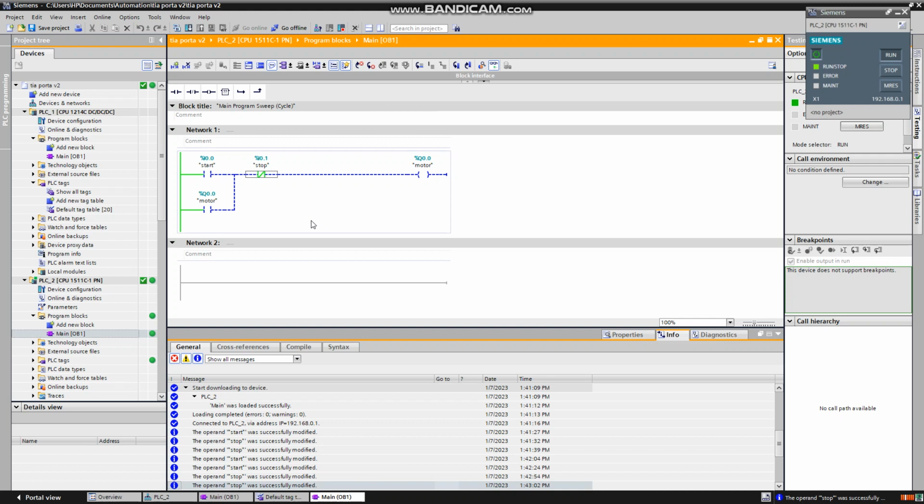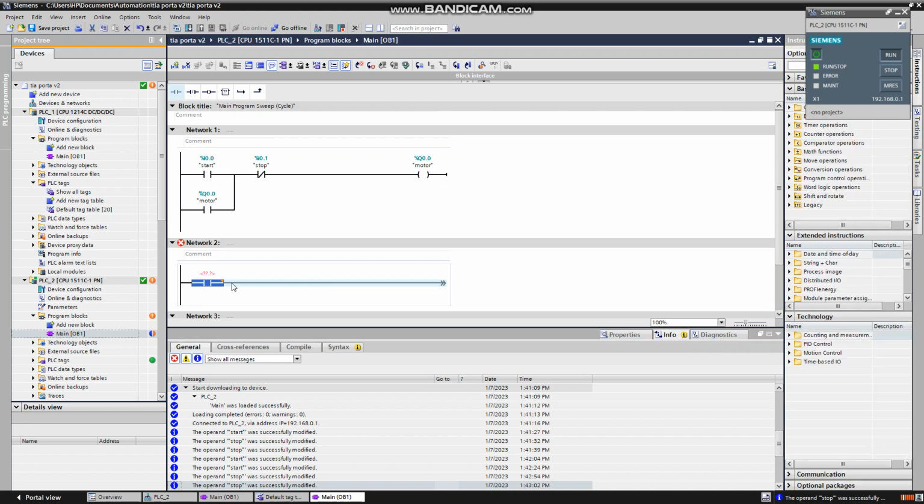Also we can make this with set or reset functions, and they are good and eligible functions in PLC in normal conditions. Set and reset functions are used frequently, so let's try it with them. Oops. We add a contact again, and get a coil.